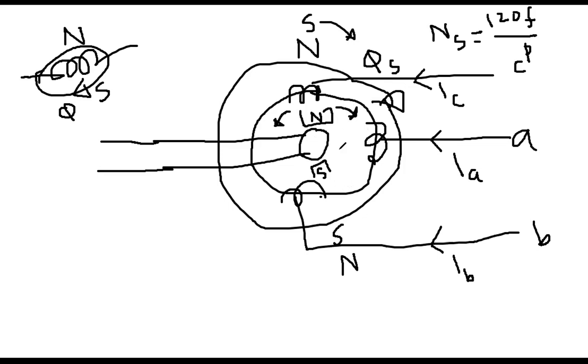Why can it not go? Because it has inertia. You see? From physics, you know, it has that inertia, because it has a specific weight, it has a specific mass. So it cannot immediately start moving. Depending on the North Pole, South Pole alignment position, either it will be repelled or it will be attracted. That's why it will just vibrate a little bit in direction, but it cannot be fully synchronized with